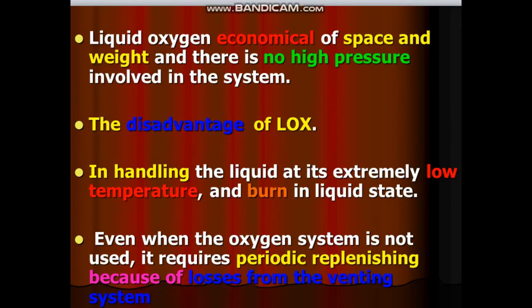Liquid oxygen is economical of space and weight, and there is no high pressure involved in the system. The disadvantages of liquid oxygen are in handling the liquid at its extremely low temperature, and that it burns in liquid state.